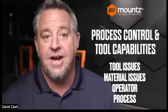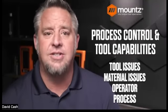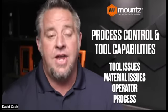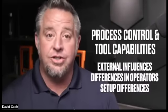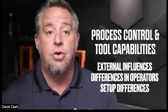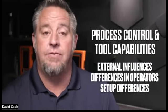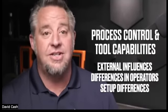There are some other factors that may be with the material that's being used. It could be the operator or the process, but if you are seeing that CMK value under 1, then this gives you the ability to focus a little bit more on the tool itself rather than what's happening around the tool. Conversely, if you are seeing a CMK value between 1 and 2 or above, then you know that you can look at the external factors that may be contributing to the process. So are there differences in how the tool is being used from operator to operator? Are they setting up this tool or using it within the process in a way that might be different?